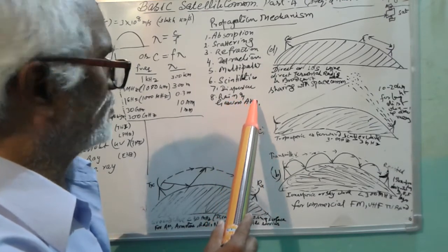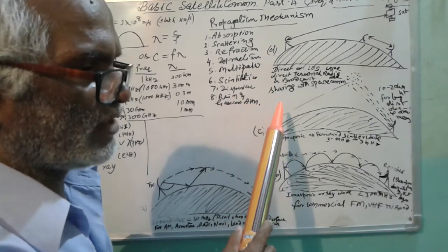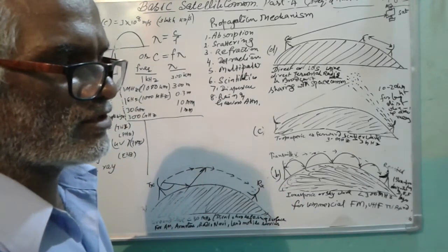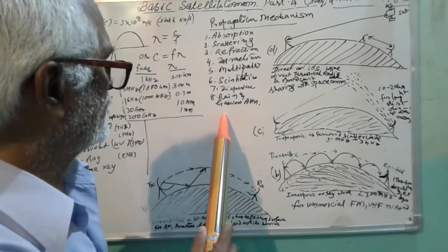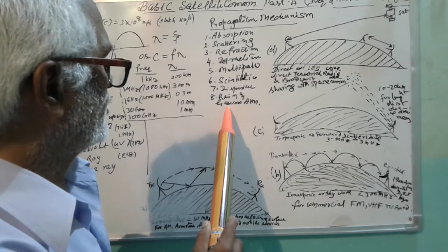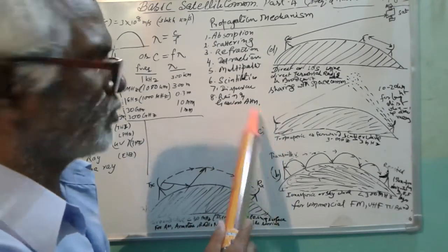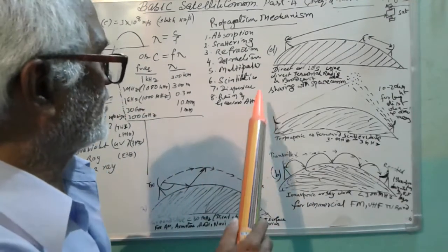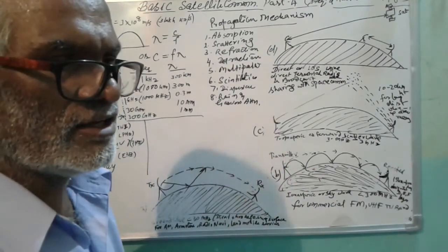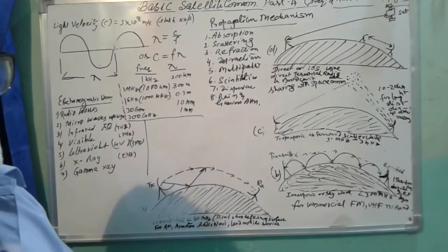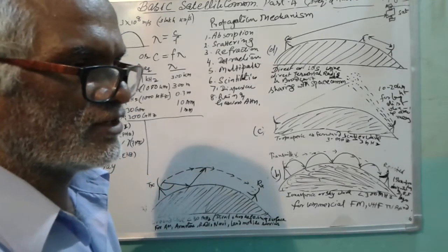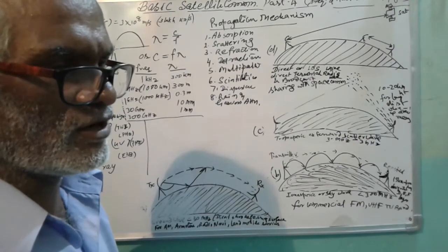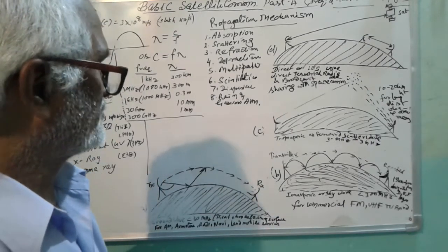Rain attenuation varies according to the frequency squared. Say at 10 gigahertz, whatever attenuation takes place, at 20 gigahertz, 4 times attenuation will take place. And for that, different methods are employed to avoid it and give a sufficient margin for the availability of the communication.